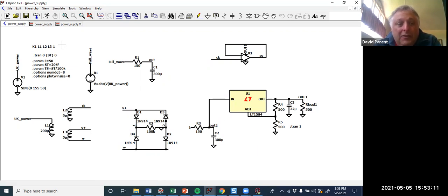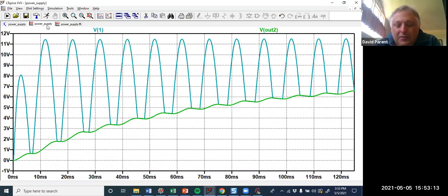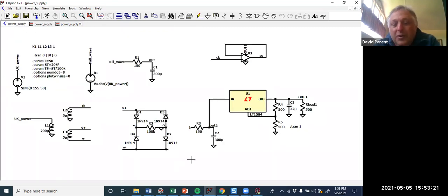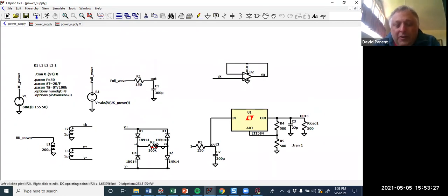By attaching the low pass filter to this circuit, it's actually affecting how it works. All right, so if I look at L2, here we're getting our DC signal eventually. Now, this is like the bonus. If I were to change the load here, that 100K is the load, right? If I put in a different resistance because I'm powering something else, it changes the whole filter characteristics. And you don't want that to happen.